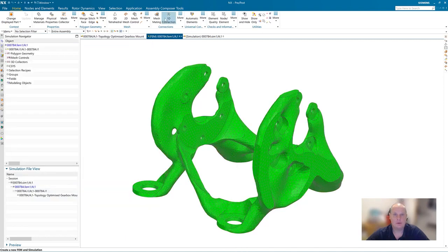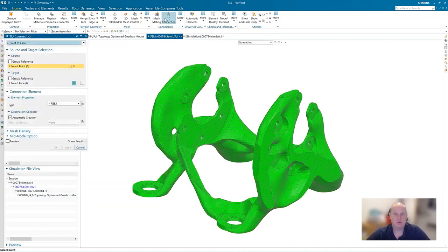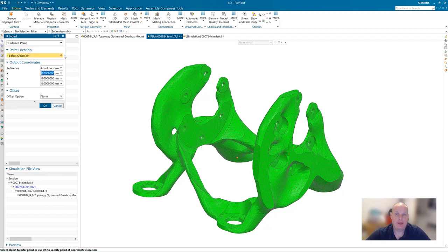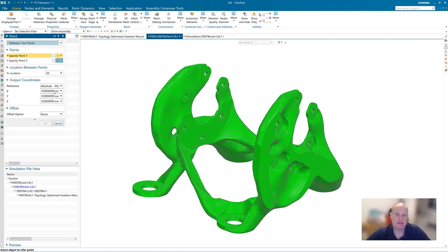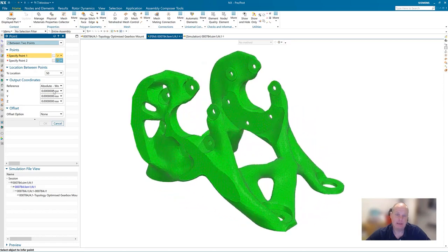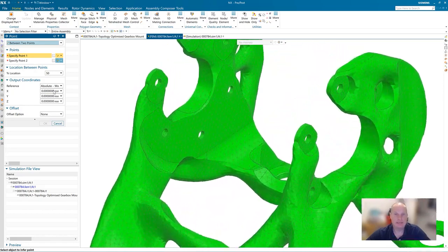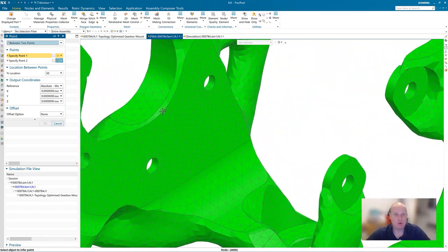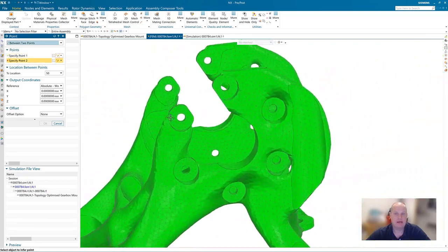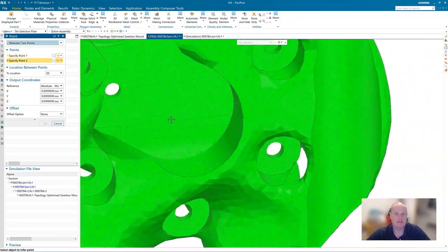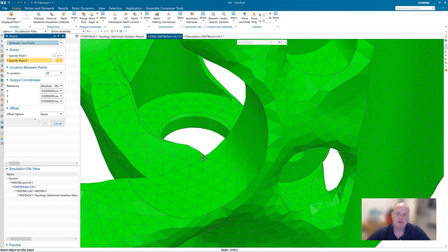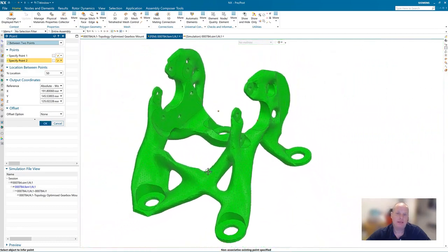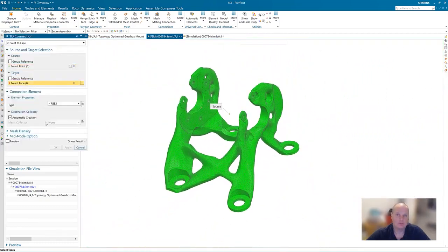Now we need to create a rigid element with its base node at the approximate location of the center of mass of the gearbox that attaches to this mounting bracket. We don't need to be exact for this analysis, as we are only trying to provide baseline guidance to improve the quality of the design. Use the between 2 points method to get an approximate location.